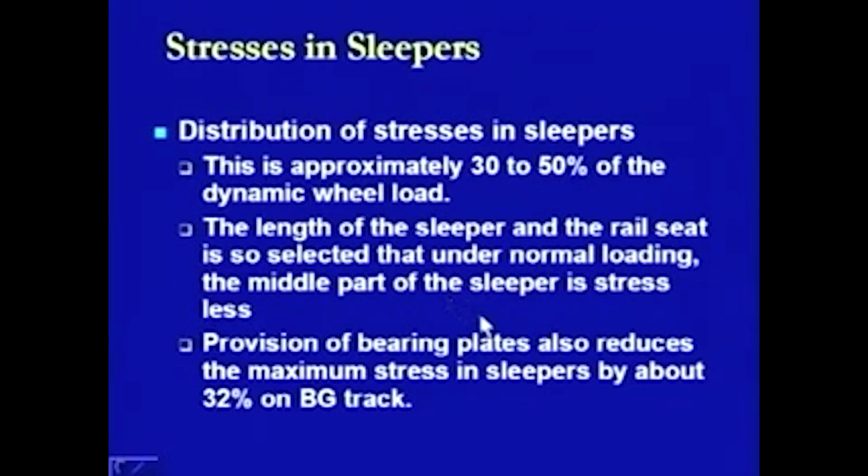What it means is that whatever is the load induced at the point of application of the rail, where the rail is connected to the sleeper through the rail seat, there is going to be more stress at that location, but as we go along the length of the sleeper, these stresses should start reducing, and as soon as we reach the center point of that sleeper, it should become 0, that there should not be any stress at the center. And this is the design principle of any sleeper.